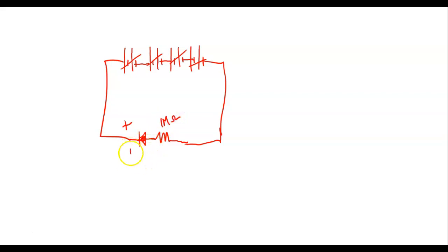I've got a meter across the diode. And then I've got 1 meter across the resistor. So they're calling this R1, I think. So BR1, it's 1 mega ohm. So I can calculate I of the diode by using V of the resistor, right? The V of R1 divided by 1 mega ohm. That's what we'll use to calculate the diode current because it's a series circuit. And what's the same in a series circuit? Current.